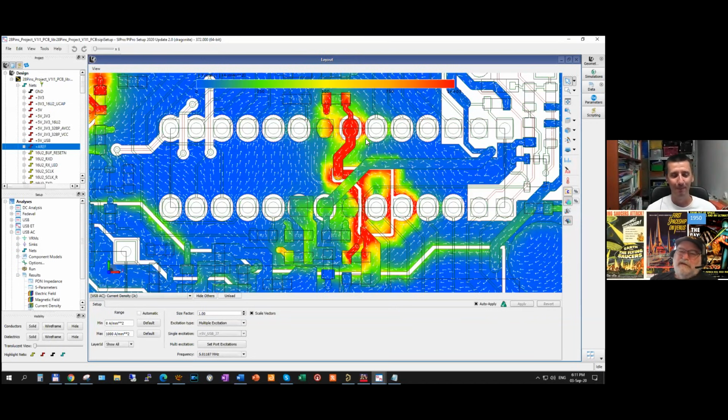You're right. And this is one of the most important concepts in signal integrity. In fact, maybe every problem in signal integrity is tied to or related to that return path. And when we look at signals, even low frequency signals in the audio range, you can't think of just the signal path and design the signal path. You have to think of the signal and its return path.